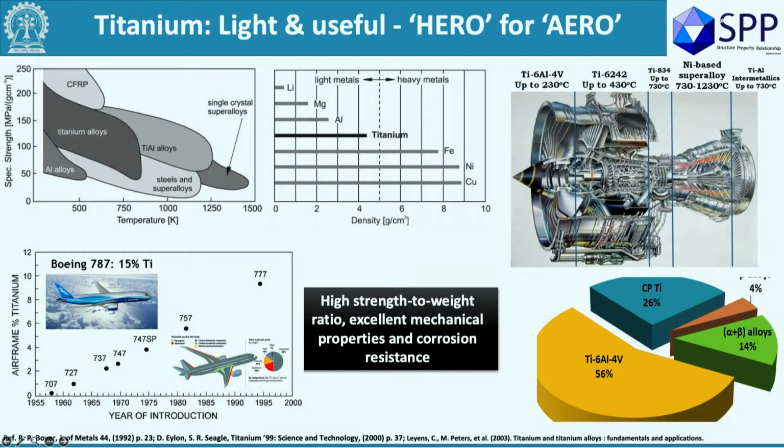He gives it to me. These are the 3 light metals. Out of that, titanium is the heaviest and most suitable for aerospace application because of its temperature capability. Titanium has higher specific strength, of course, and high temperature capability. The best thing is high temperature capability. Aluminum and magnesium don't have that.